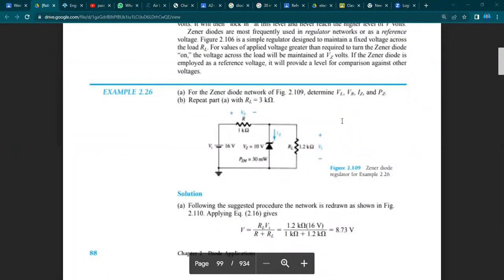Zener diodes are diodes which work in the reverse direction. There are different types of Zener diodes with different breakdown voltages. When forward biased, it behaves the same as a normal diode. But in reverse bias, the Zener diode starts conducting and behaves as a forward biased diode. I mean that it allows the current to flow through it when the voltage approaches its breakdown voltage.